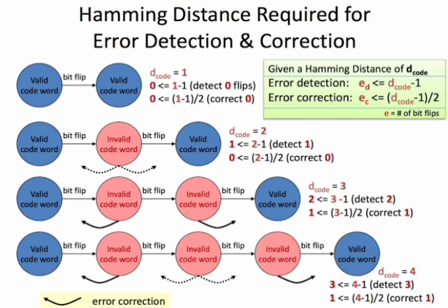Coaxial cable is also used for connection making with connectors BNC, Bayonet Neill-Concelman connector, and TNC, Threaded Neill-Concelman connector. Amplitude distortion. This type of distortion results from production of new frequencies in the output which are not there in the input signal. These new frequencies are caused due to non-linearity of active devices.